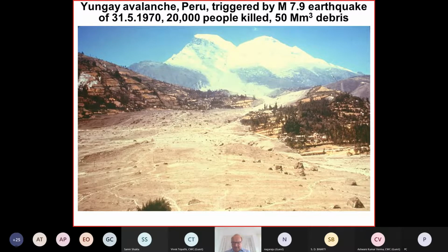But I just want to say this is not new, but if such debris, which here was about 50 million cubic meters, of course, encounter some dams with smaller reservoirs, I must say to cope with 50 million cubic meters of debris flow, you would need a reservoir of, I don't know, 200-300 million cubic meters in order somehow to account for such or to block the propagation of such debris flow.